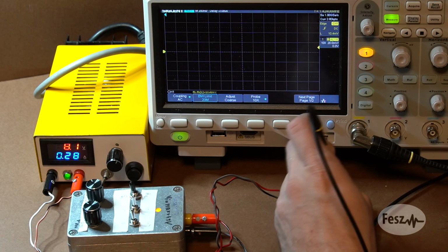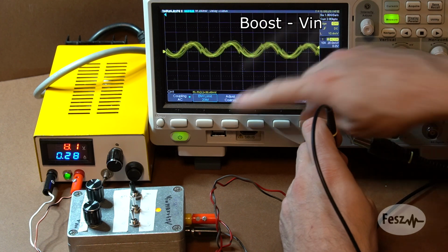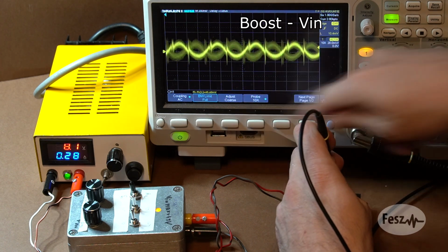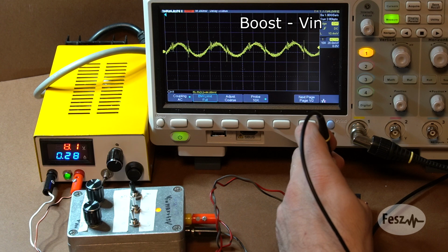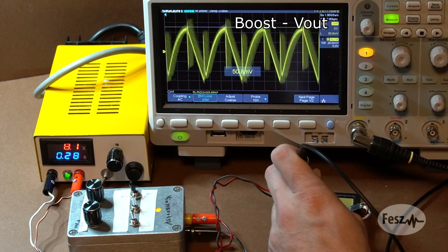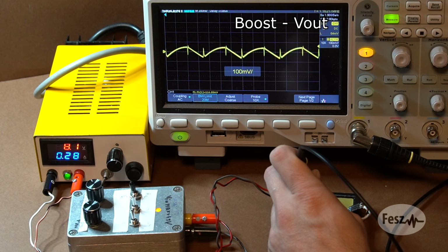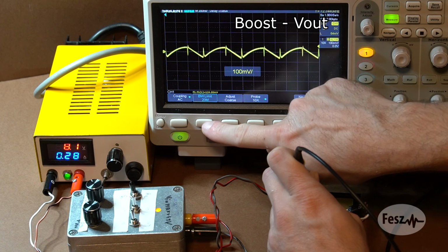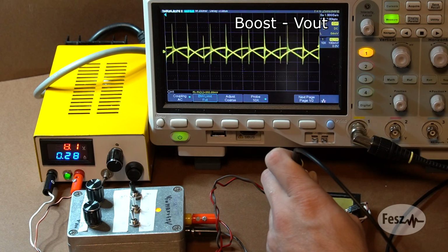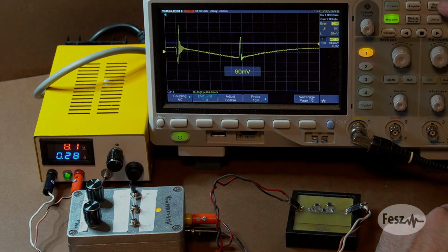Now, if the noise measurement on the input and output is done with sufficient bandwidth, you will also see that other than the non-ideal waveform we looked at previously, we also have some spikes appearing. Now, while usual noise measurements are carried out with a 20 MHz bandwidth limit to measure the exact ripple, if you want to see this high frequency noise, I do suggest to leave your measurement device with higher value bandwidths.